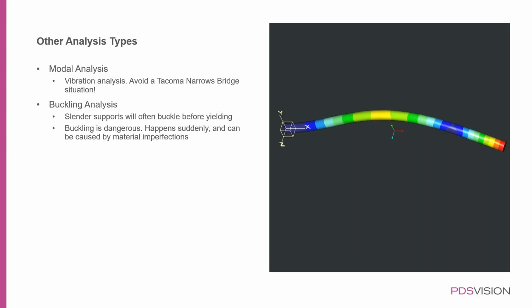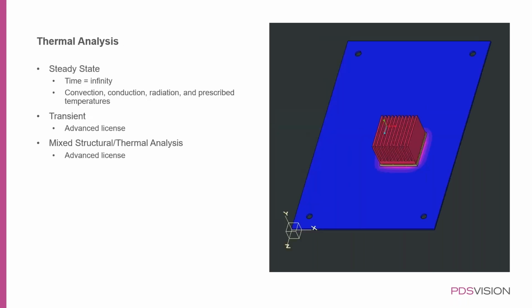Additionally, buckling can be caused by material imperfections. So if you're getting bad quality steel, then you're going to want to be more worried, because little imperfections can make buckling much more likely. So those are all the reasons that you're going to want to start simulating buckling if you're not already doing that and you're dealing with compressive axial loads on narrow parts.